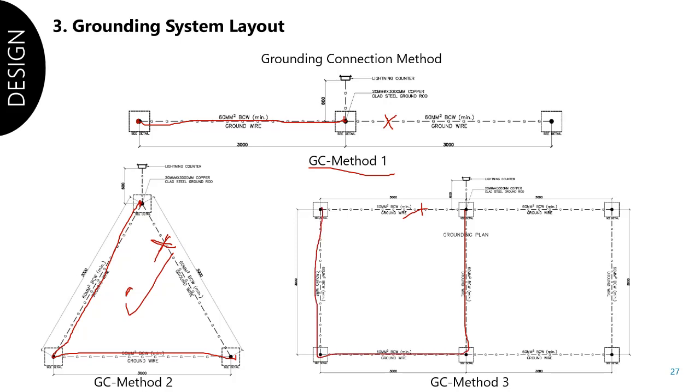Can connect to each other and still can connect to each other. So that's the advantage of a grid, grounding, and triad. But basically, or mostly, I use a triad design for my lightning protection system. So I think a triad design is enough for our lightning protection system. Of course, if it's not enough, you may need another ground rod to be buried just to compensate, or just to have the required grounding resistance for it.